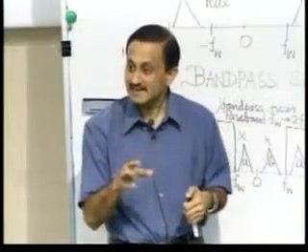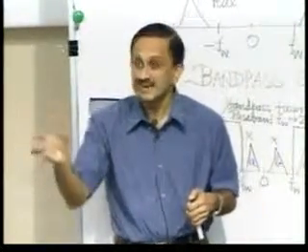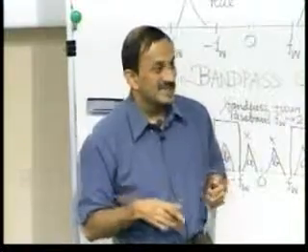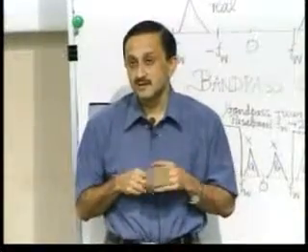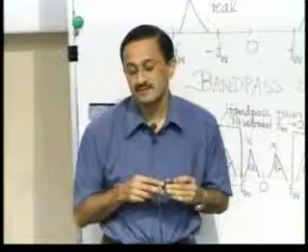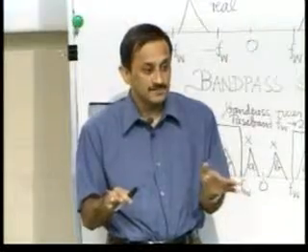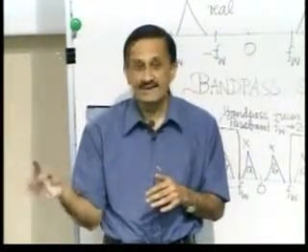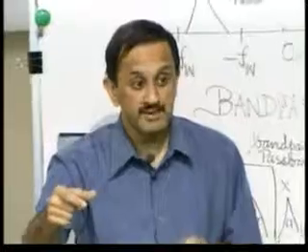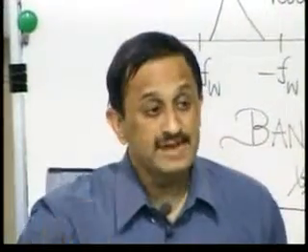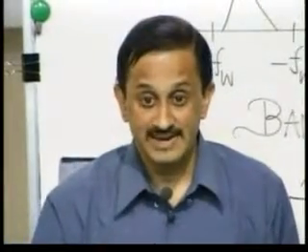If you think about it from that perspective, there is a broader philosophy. If you put in a little more a priori information, you can use that cleverly to reduce the requirement on sampling. That can be taken further, and at this point, as far as sampling goes, with a caveat: if it is only band limitedness that we are assured of, then the Nyquist principle says you must sample the signal at least at twice the maximum frequency component. But if you have a little more than band limitedness, for example, if you also know the signal is band pass, then that a priori information can be exploited.